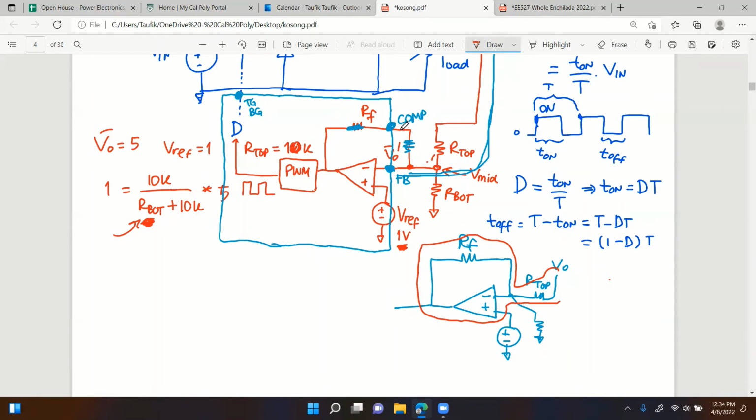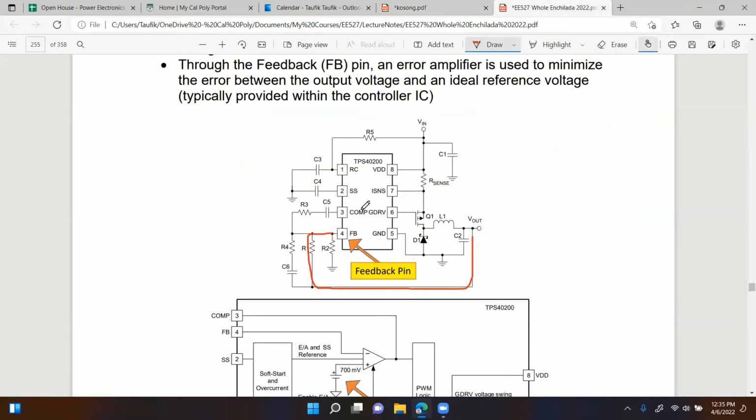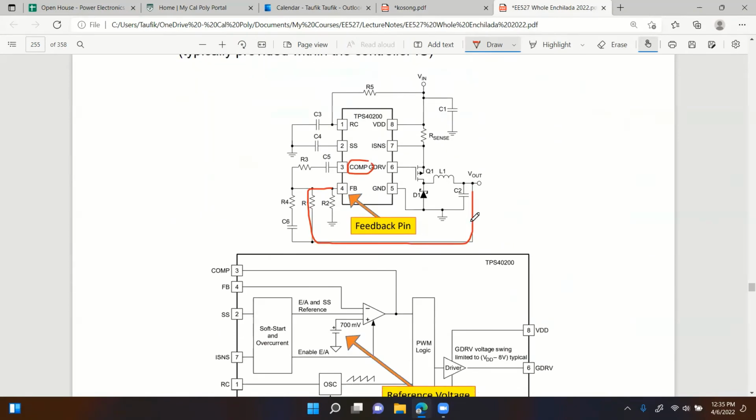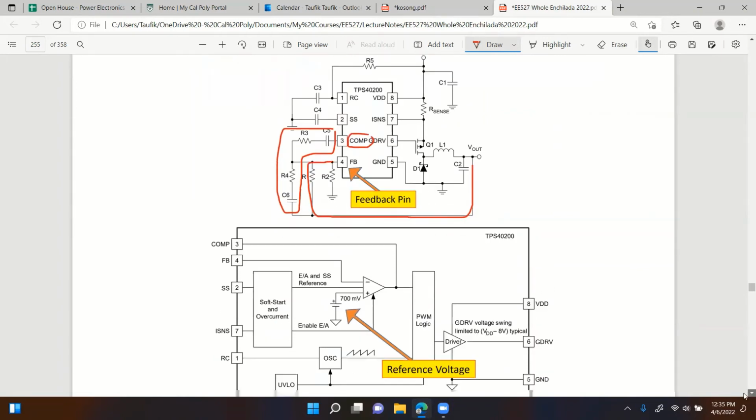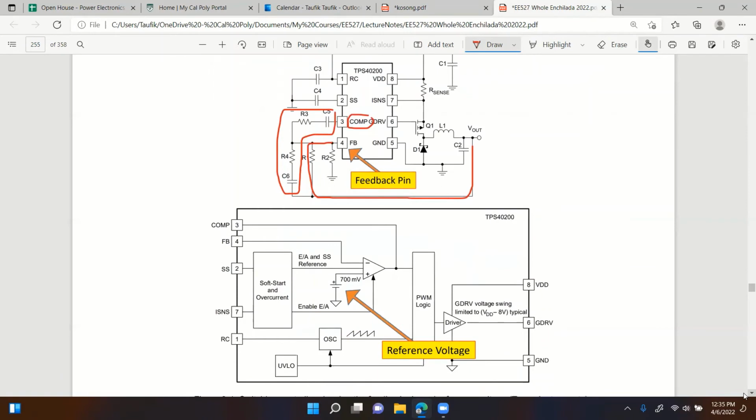That's the one that facilitates an additional circuit called the compensator circuit for us to add, right? So you can see that's the pin right there. As you can see, it is connected to the op-amp. Remember, there is an op-amp inside right there. So it's connected to that. And this is a type 3 amplifier. You can see there's a network right there. There's a compensator connected to the comp pin right there.